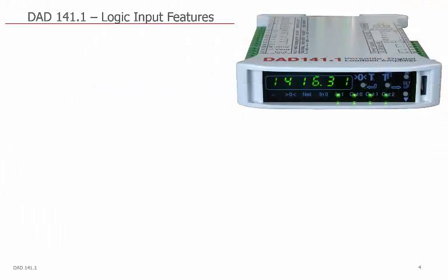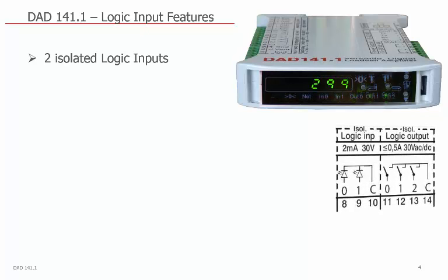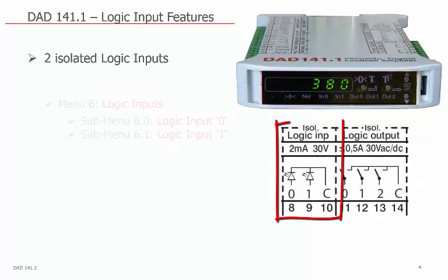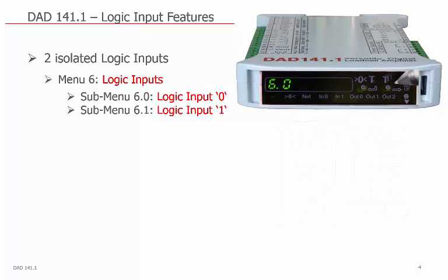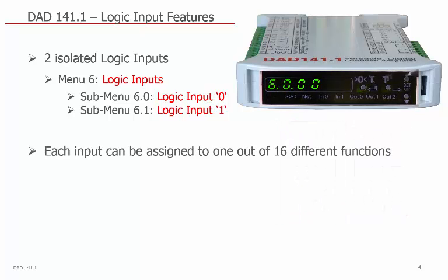The logic input features. The DAD 141 has 2 isolated logic inputs. Menu 6, setup for the logic inputs. Submenu 6.0, setup for the logic input 0. Submenu 6.1, setup for the logic input 1. Each logic input can be assigned to one out of 16 different functions.